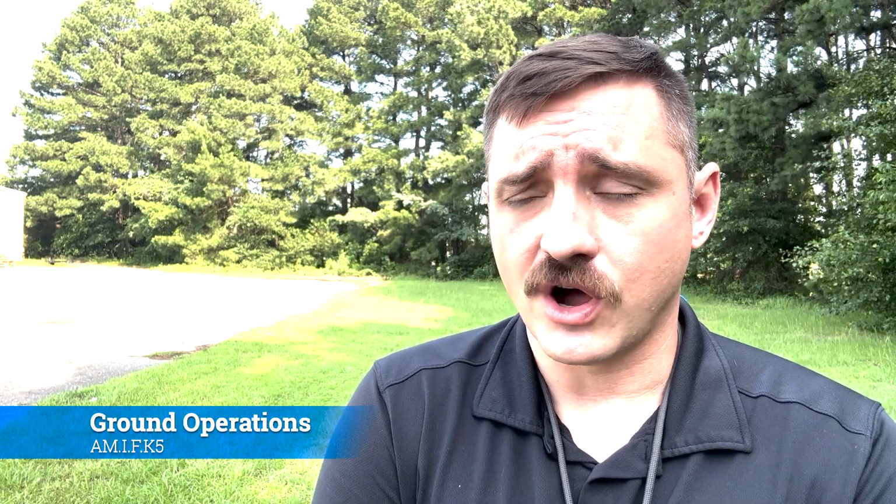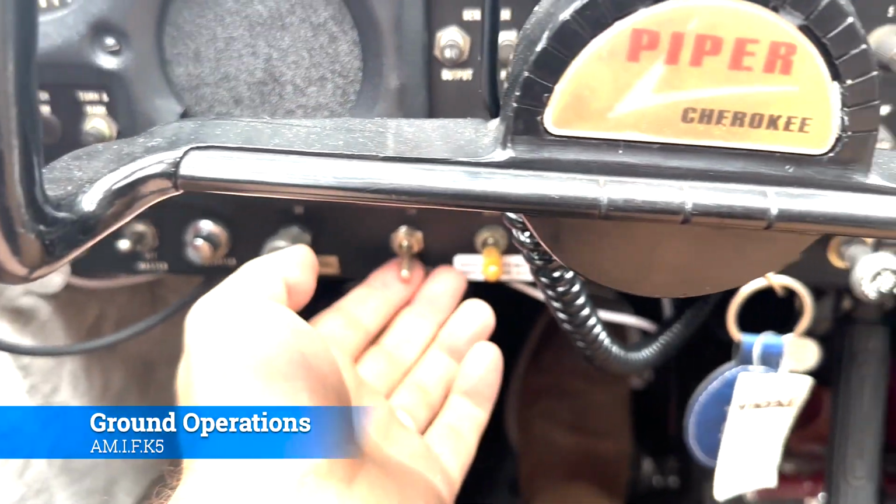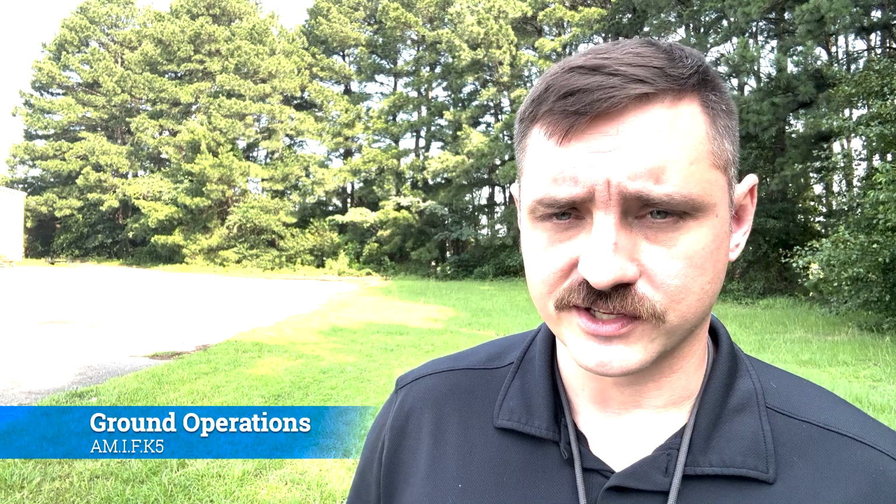And because of that, there are all different types of engines, aircraft, configurations, and technology differences, so there's always going to be some variance, but generally speaking, they will follow these procedures. First thing, you're going to turn the fuel pump on. You're going to supply electrically powered fuel all the way up to the engine, so that it's ready to grab that fuel and start working as soon as you hit the starter.